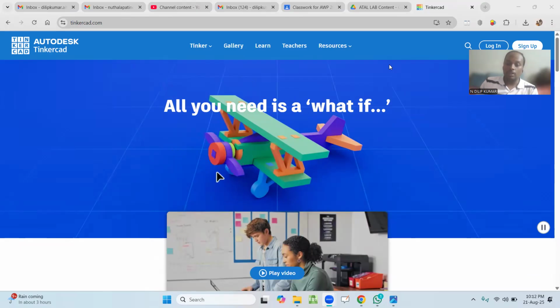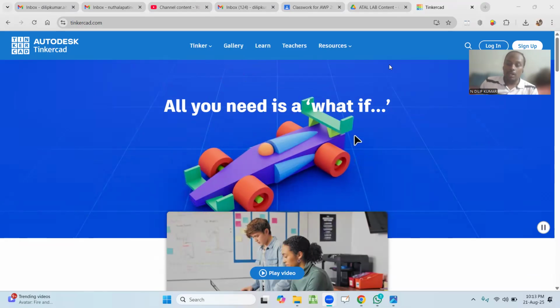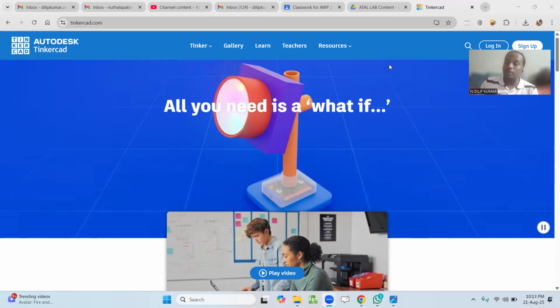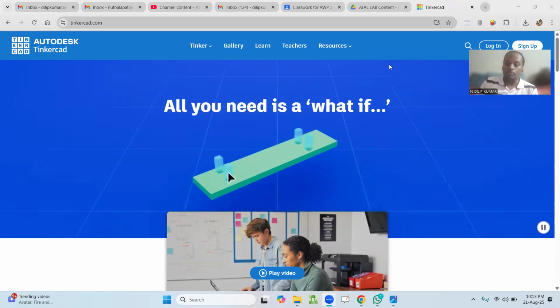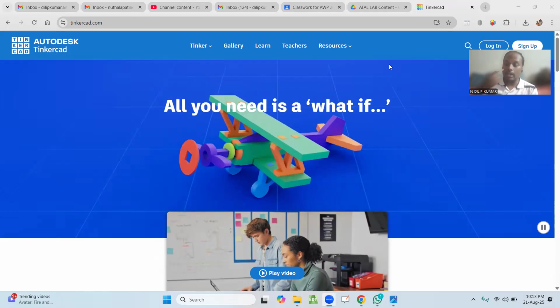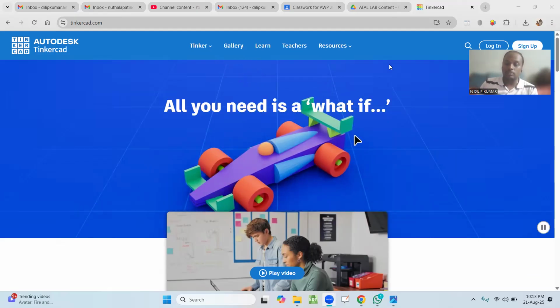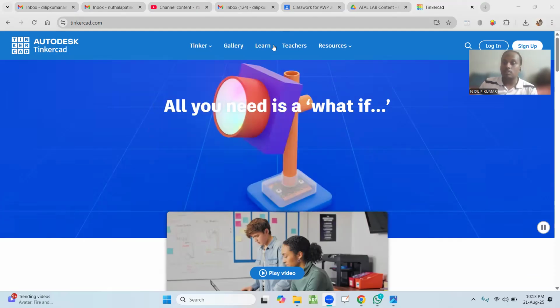Whereas a parallel circuit is one in which all the components are connected across the same 2 points, that is, side by side, so there are multiple paths for the current to flow. Here the current is divided into the respective paths, the voltages are the same, and the currents are divided across the respective branches depending on the resistance in the respective parallel branch.